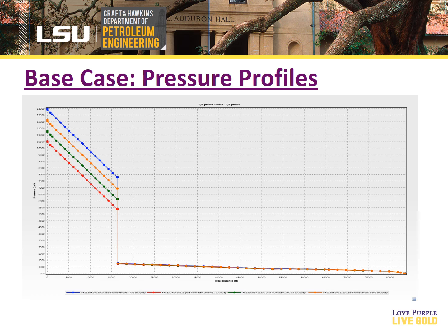The first graph we're going to look at is the pressure profile of the subsea system. As a fluid particle moves from the bottom hole up the well bore, through the choke, into the manifold, up the flow line to the surface separator. The steep decline in pressure represents traveling up the wellbore, and then the near vertical line represents the pressure change crossing the choke. The multiple plots you see here represent the pressure drawdown characteristics as the well depletes in 3.75 years.